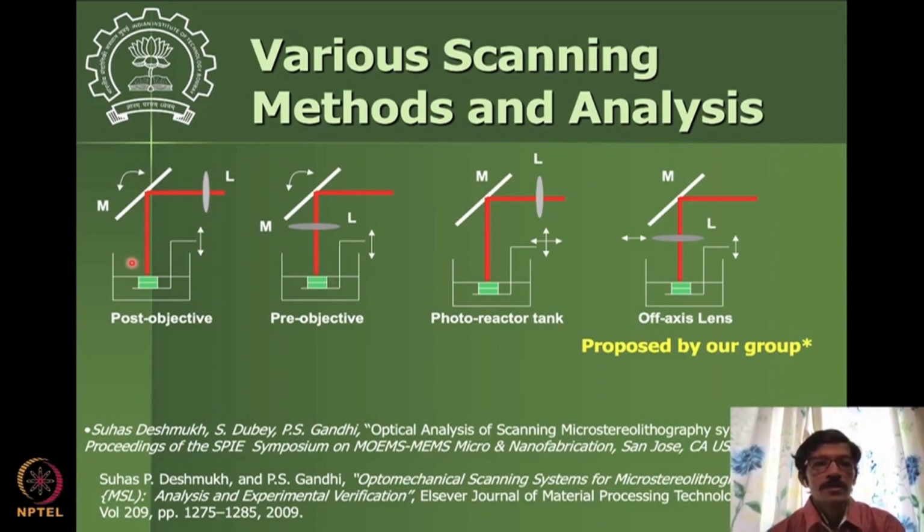For example, in this system, the scanning goes over a sphere, and the surface on which the photopolymerization happens is flat. What happens is that the laser gets defocused at the other places, and when you want to create a micro scale component, you need the laser focal length to be very, very small, so that the focal spot is small in size.